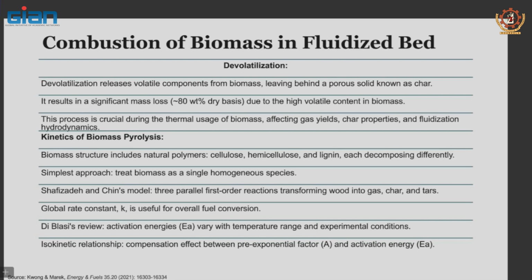So it's significant. Why am I saying this? Because you have to understand that when the volatile matter is burned, it is much faster. Therefore, a lot of heat is released at that time. You need to be able to capture it.